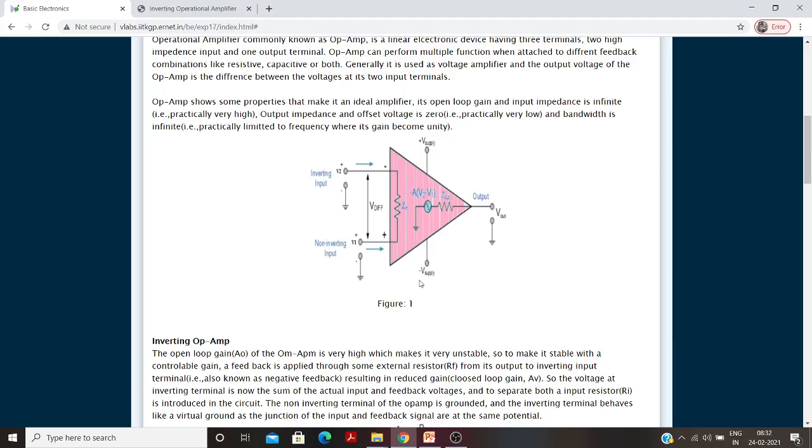If we give input to the inverting input, this pin number 2, and if you have not watched the videos on pin configuration, you can watch them too. I have explained each and everything there, how to use it and the pin numbers. If you give voltage V2 to the inverting input and ground V1, the configuration is called an inverting amplifier.